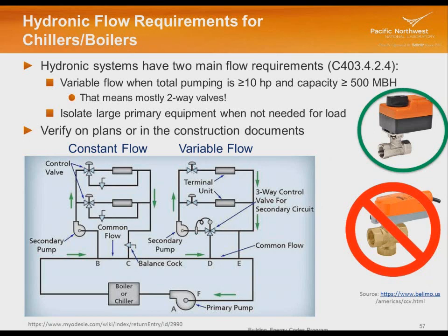And in fact, we can even look at whether we have a pressure sensor out here, and we're looking at all these valve positions, and we can slow that pump down until one of those valves is almost fully open, or the pressure comes down to what we know will work for all these valves. And that's part of the VSD requirement on the pump.